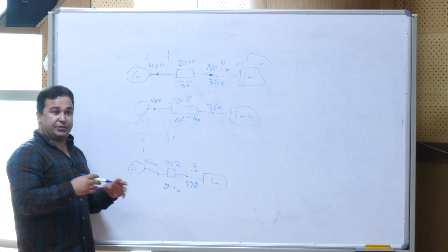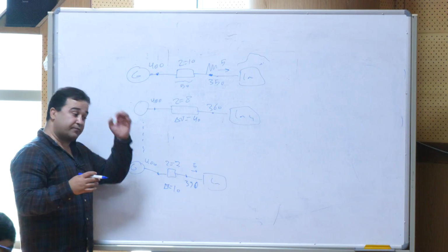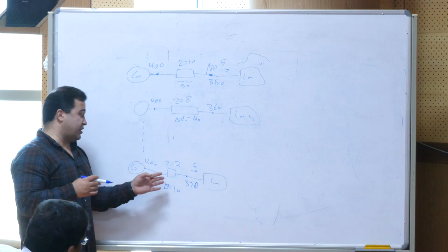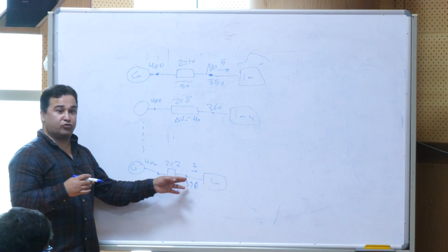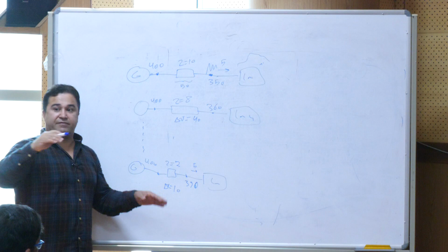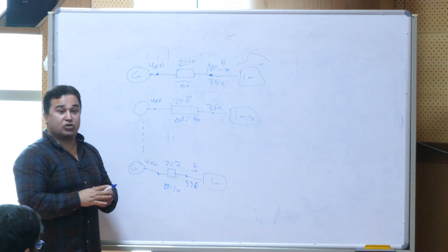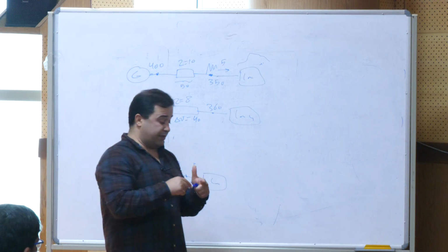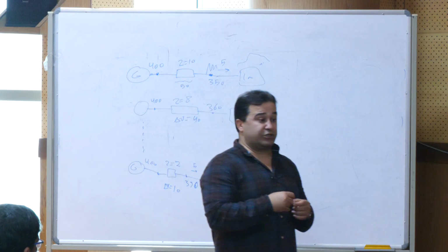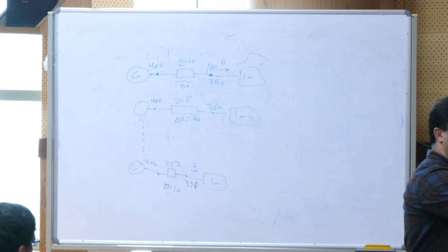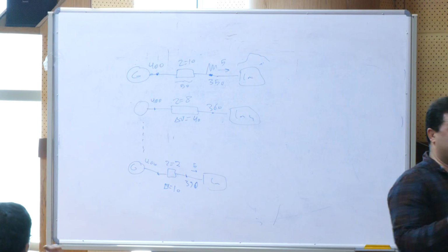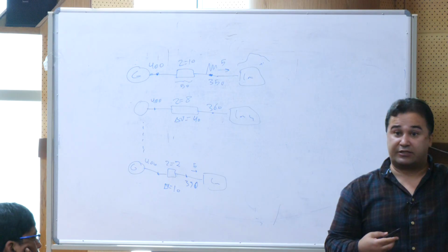In fact, the impedance over the grid is somehow almost similar to the voltage of the point of common coupling, and anything happening, we have a stable voltage there. So by this, when we increase the share of renewable energy sources in the power grid and also reduce the number of synchronous generators, the impedance of the grid increases.